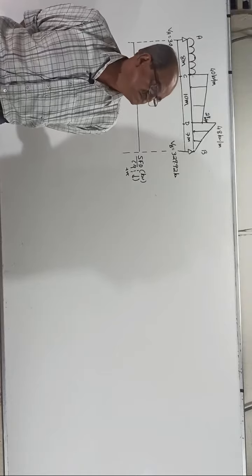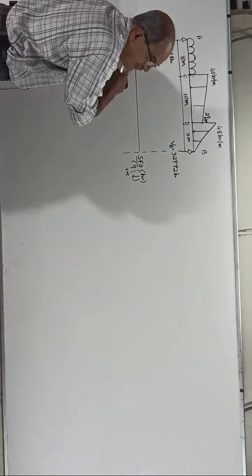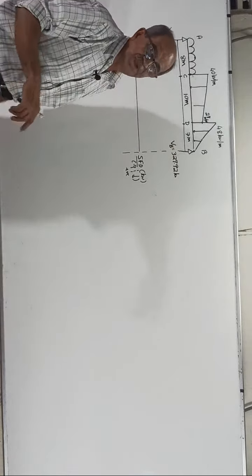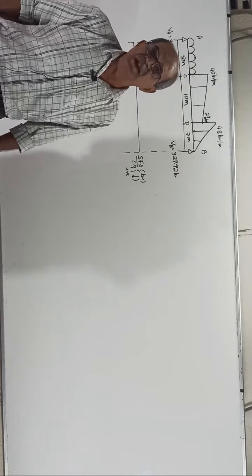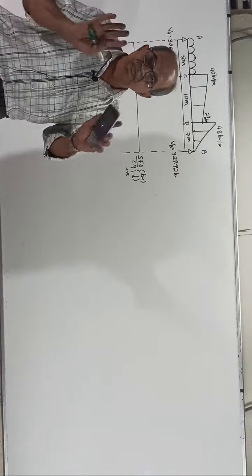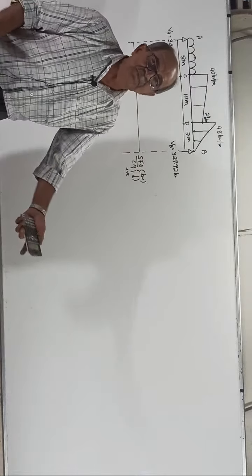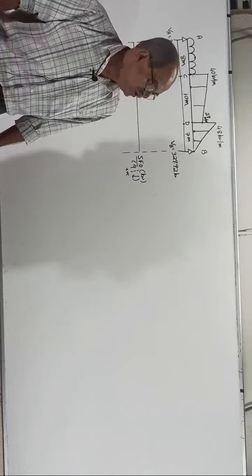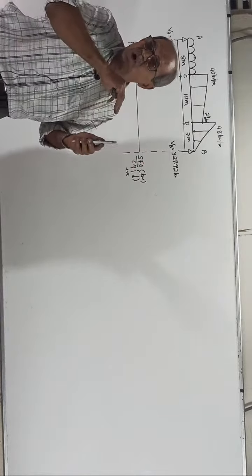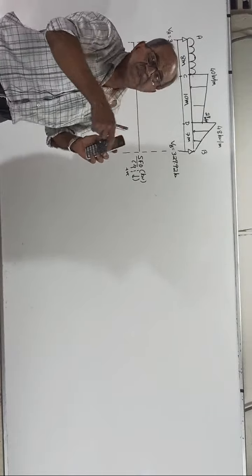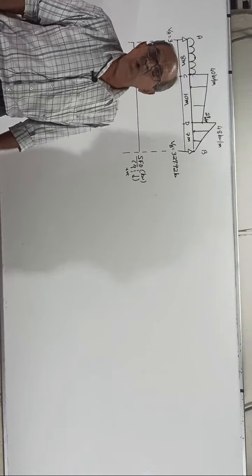All bogus. For BMD, if a clockwise couple is there, if you start from the left side, yes, correct, the BM ordinate will jump. BMD will not jump. BMD will remain there only. What BMD jumps? If you jump, you can't tell the earth is jumping. You are jumping. But if you start from right to left, then if a clockwise couple is there, the BM ordinate will drop. So that is actually a very crude way.